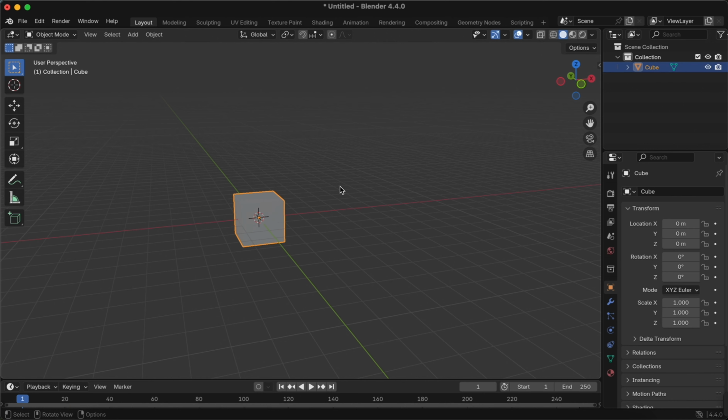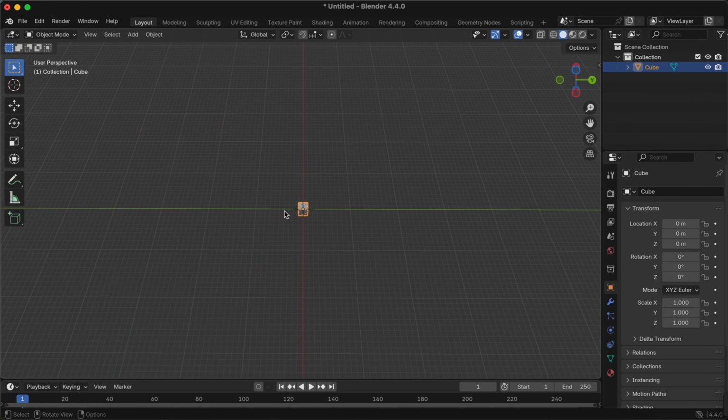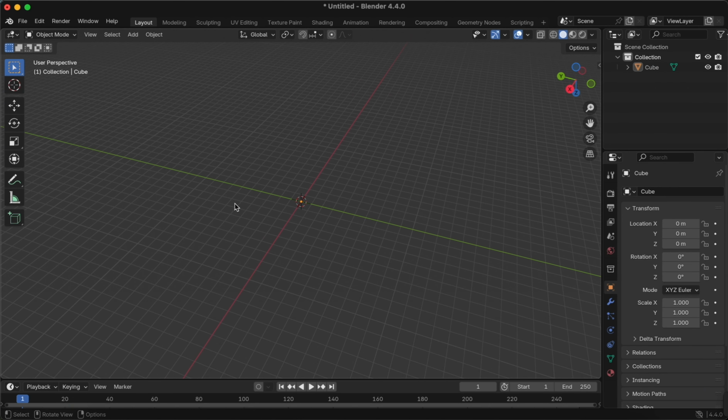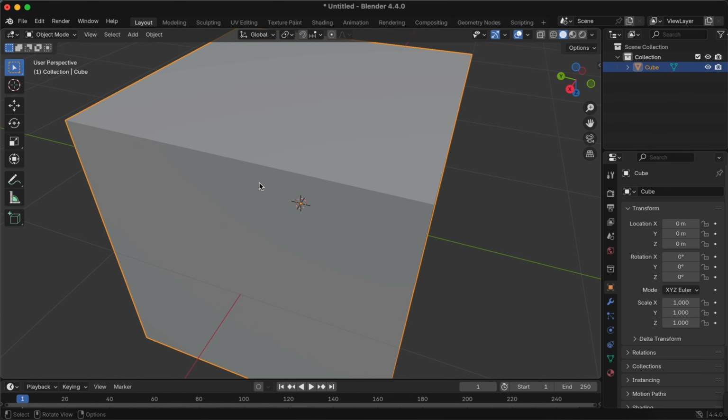If you somehow, let's say you lost the Blender viewport, or we mistakenly can't see the objects, in order for us to find it, you can click on the objects, then go to View in this viewport panel, then select Home, or select All, which is the same as Home.